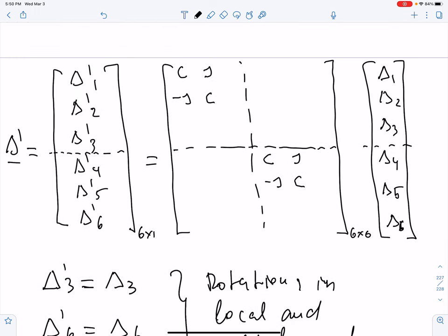And so what that does is it allows me to put a 1 here and a 1 there. The rest of that matrix just gets populated with zeros, because I reflected all the relationships that I wanted to reflect. The displacements are related to each other through a usual rotation matrix, sines and cosines, and that rotation matrix is expanded to include a 1 for the rotational parts.